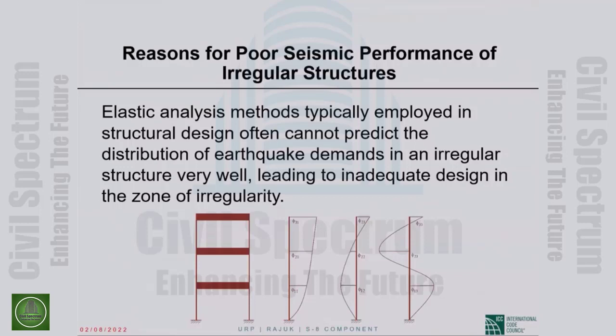Elastic analysis methods, which is what we almost always use as the basis of design, whether static or dynamic, doesn't make any difference. Elastic analysis methods typically employed in structural design often cannot predict the distribution of earthquake demands in an irregular structure very well, leading to inadequate design in the zone of irregularity.